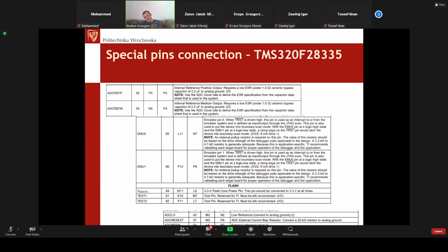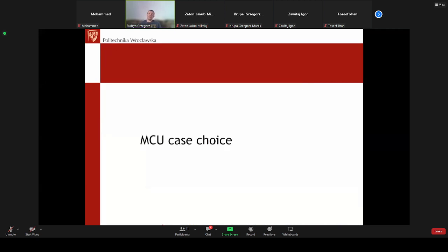But in some microcontrollers, for some reason unknown to me, even if you don't use analog circuitry, you have to configure those pins. Here in this example, these are those two pins and those three pins. If you don't connect anything to them, even the digital part of the microcontroller won't work. Why? No bloody idea. But unfortunately, sometimes it's so, so be quite careful about it.